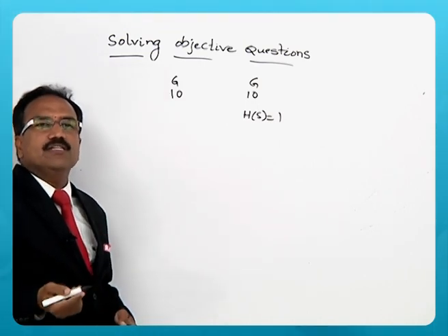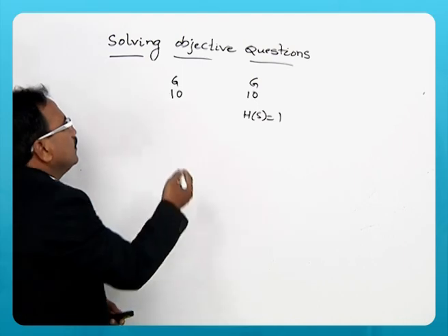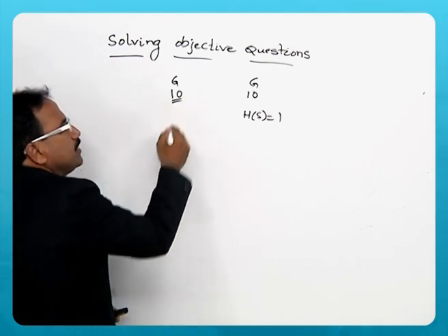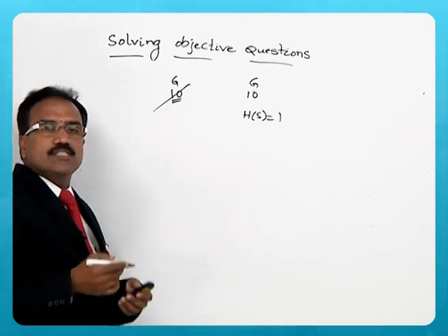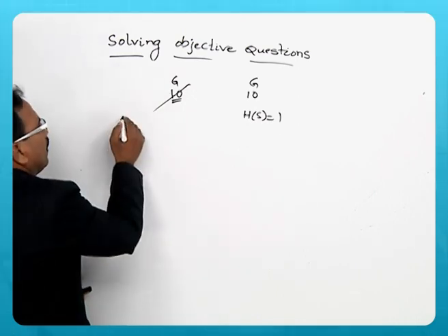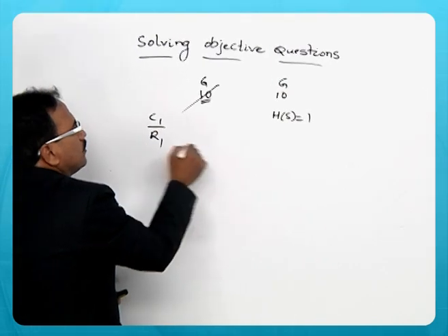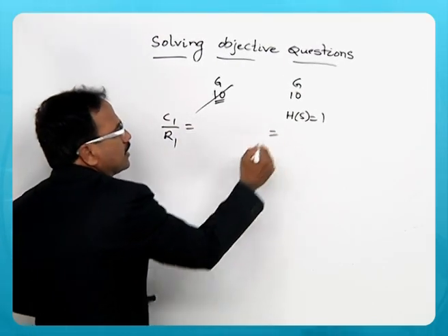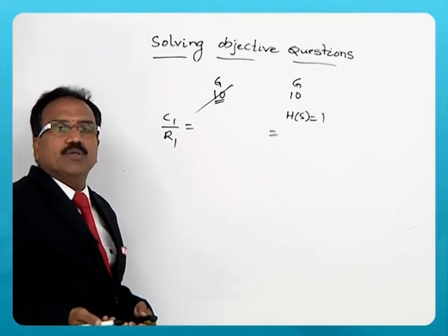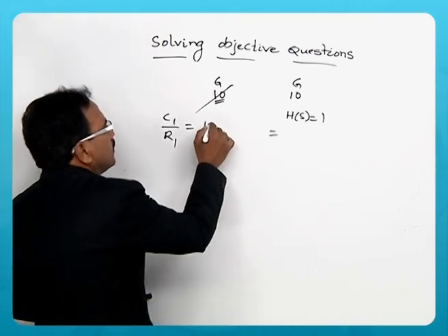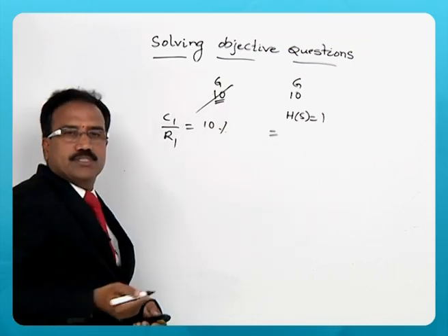If the gain is reduced by 10%, then what is its effect on the output of the open loop control system and in the case of the closed loop control system? So the effect is dominating in the open loop control system, it is 10% because the reduction is 10%.